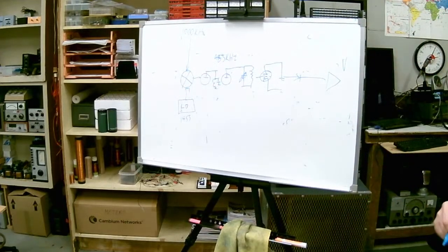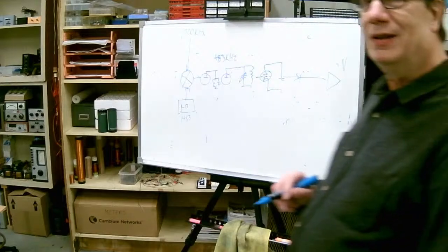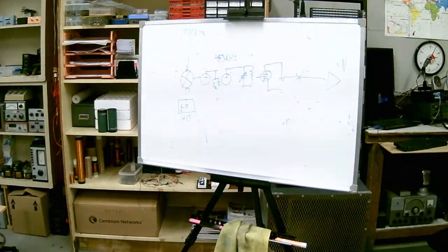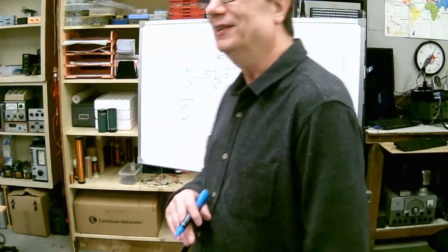Going back to the oscillator, you're saying that it takes the sum and the difference. That's called the superheterodyne receiver, or superhet, which still 99% of all receivers, whether from TV to radar, are superhet of some sort.